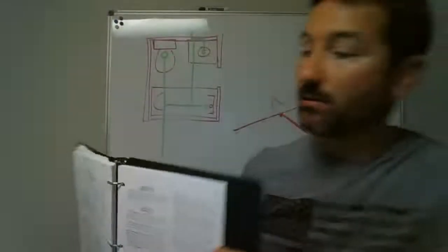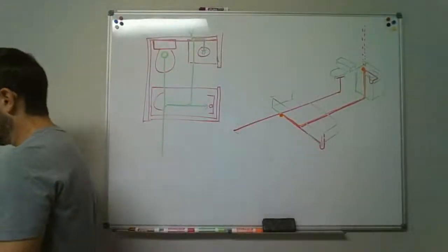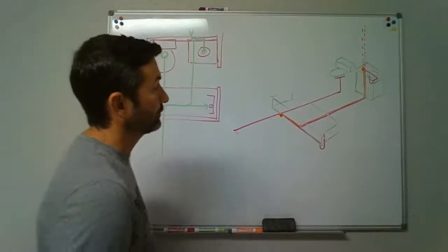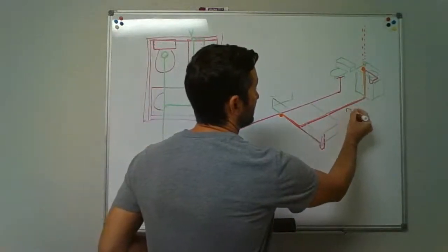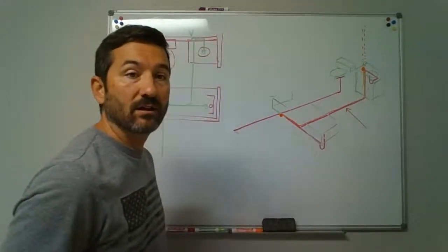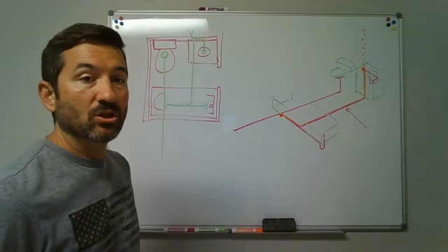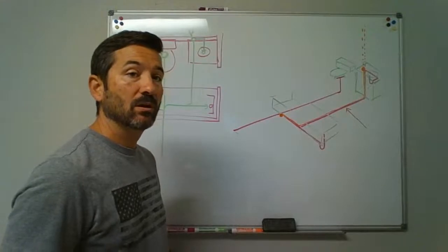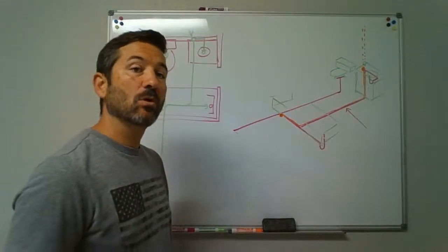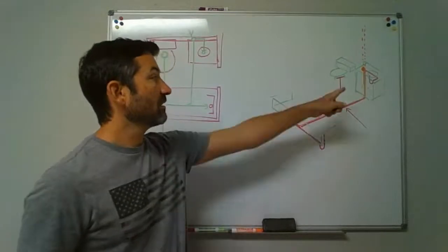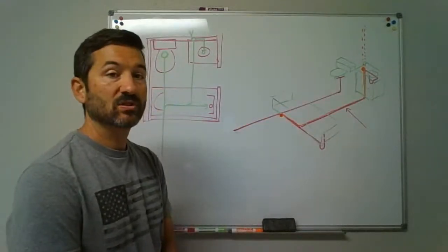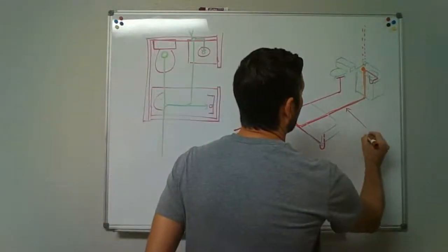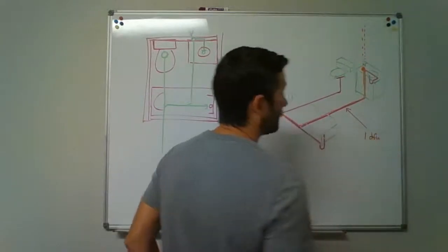Okay, so what do we do? How we use that chart is we are going to point to the pipe that we're trying to size. And let's just say, all right, let's size this section of the wet vent, and that's what we're trying to size. So you look at that and say, how many DFUs are draining down that pipe? And how you know how many DFUs is because you say, well, what fixture is draining down the pipe? It's a lavatory sink draining down it. So table 709.1 says that lavatories are worth 1 DFU. So you look at 1 DFU on that pipe.